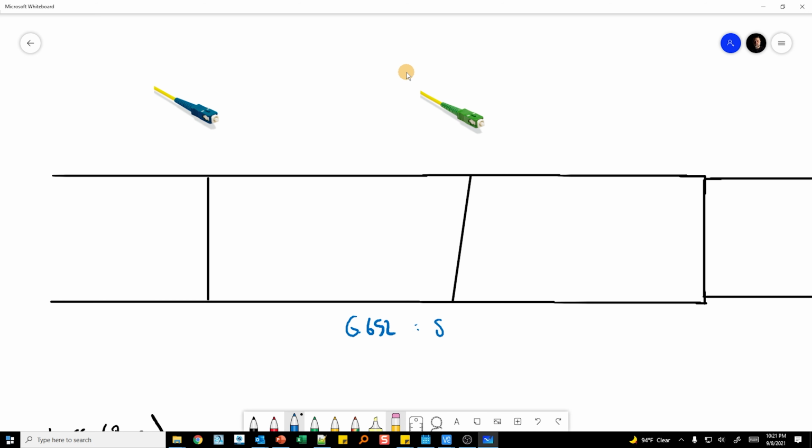We're sitting at 8.3 microns, 8 to 10 microns or whatever for single mode fiber, depending on the type of glass you have. That's basically the core size. This is not exact, so I'd have to look up the specs. I think it's 8.3 microns. That might be the mode field diameter. You'll have to excuse me; I'll check on that and add a notation.